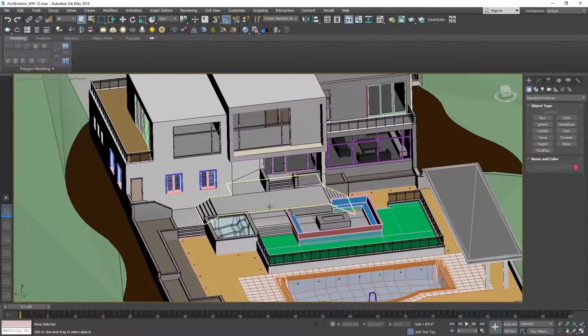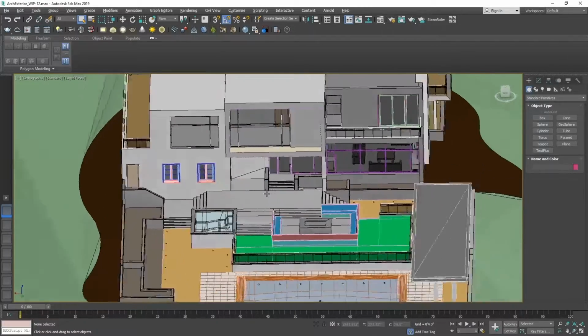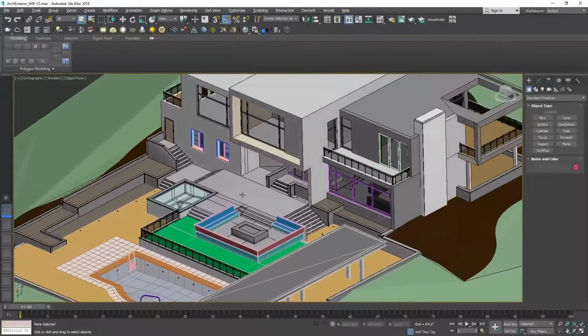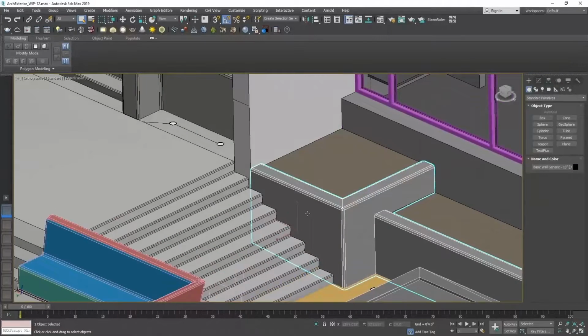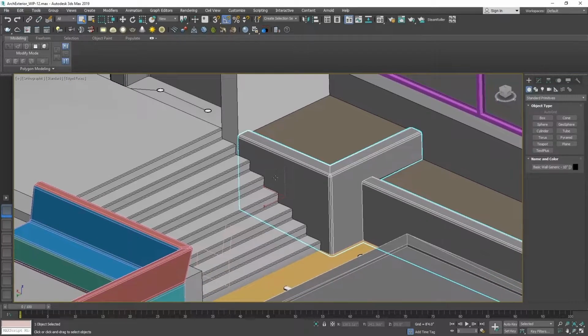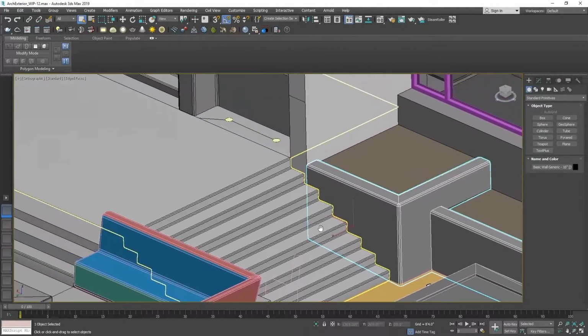To optimize this house model for Unreal Engine, a great deal of attention has been put into how the geometry is set up. Notice that all of our walls and floors terminate right at corners. If we choose to build our lighting in Unreal Engine, this will help us to have nice, crisp shadows along these surfaces. Also, notice how some of these ledges and half walls have a rounded lip. This will help catch reflections and lighting to make it seem much more realistic.